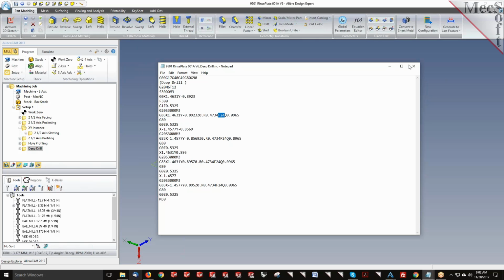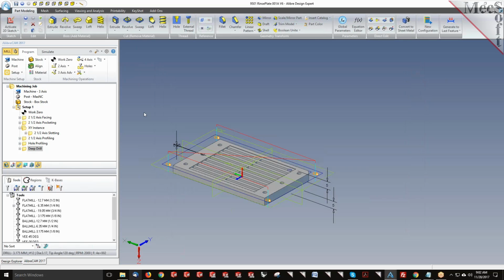Yeah, you can save them into a knowledge base. You can have a drill, peck drill, tap, maybe a sequence of them, saved for, say, material 6061. Then you just load the library and pick the holes for other projects. So you can create a template of operations.